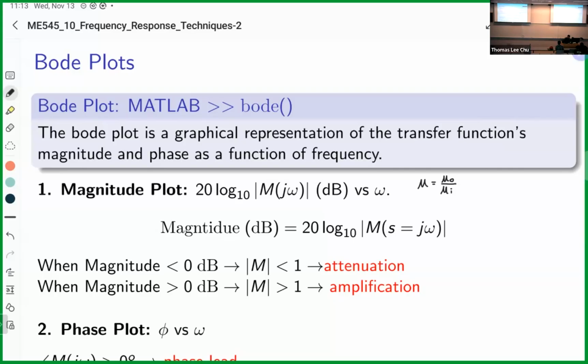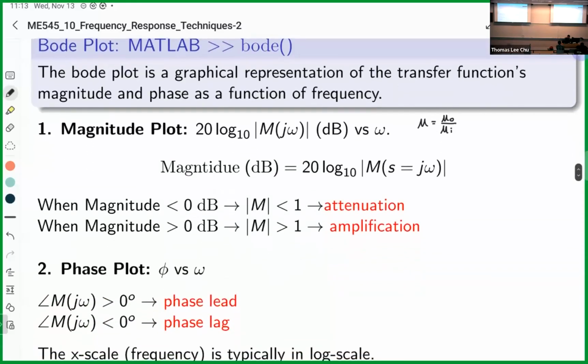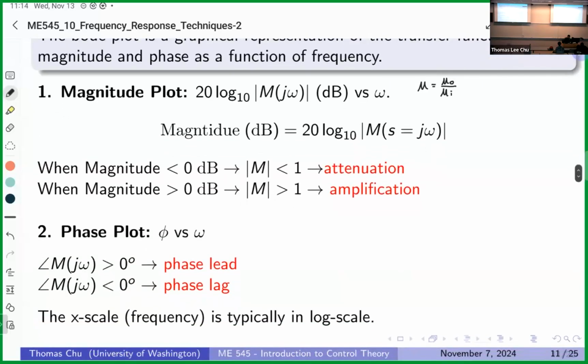So when we have a magnitude that's like -5 decibels, that means our output signal is smaller than our input signal in terms of magnitude. And remember, because it's a log scale, if we go from 0 to -3, that's going to be a reduction of magnitude by 50%. And so if we go from 0 to -10, it's a much larger reduction. It's not linear, it's a log scale.